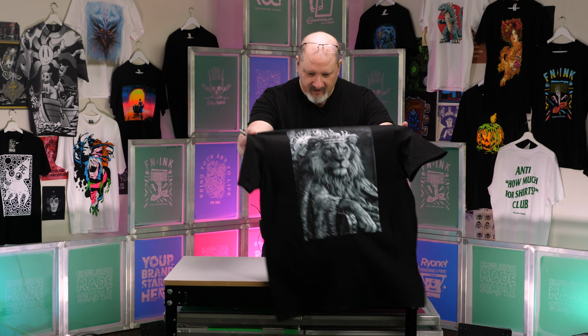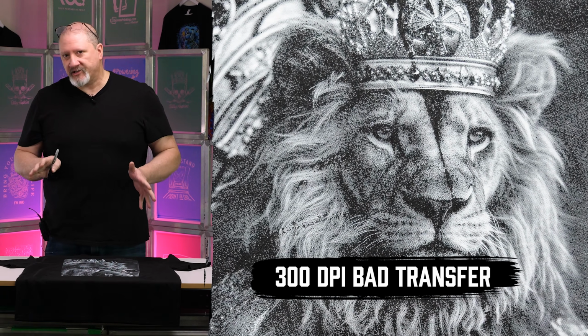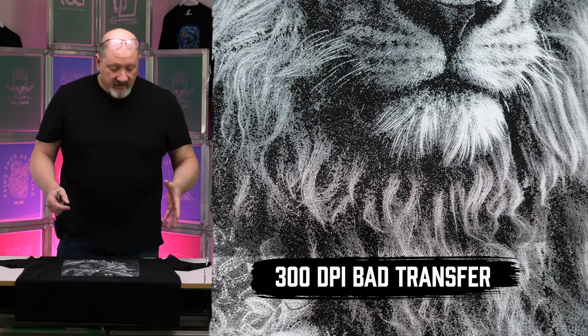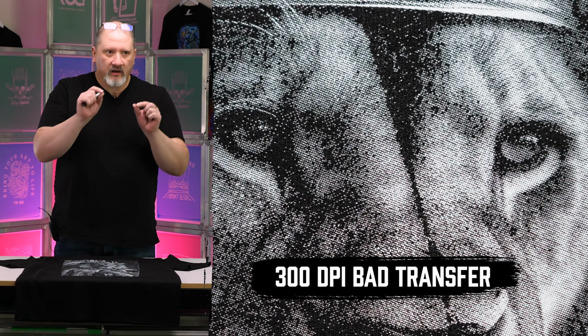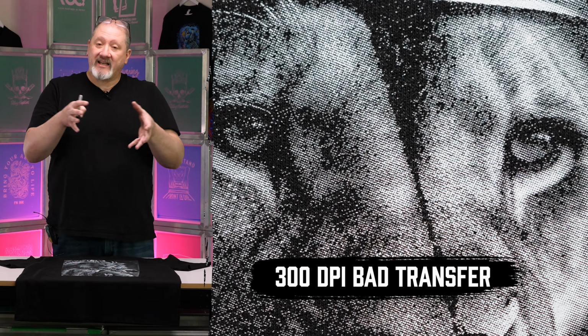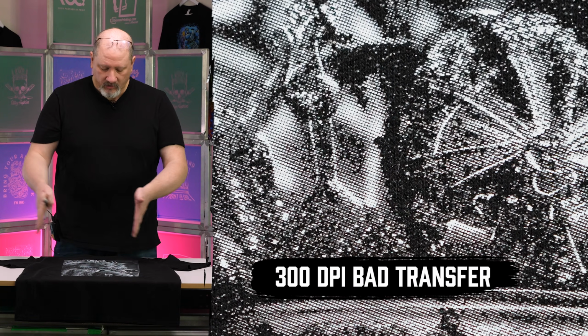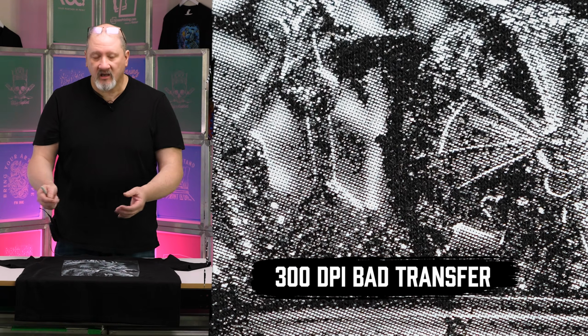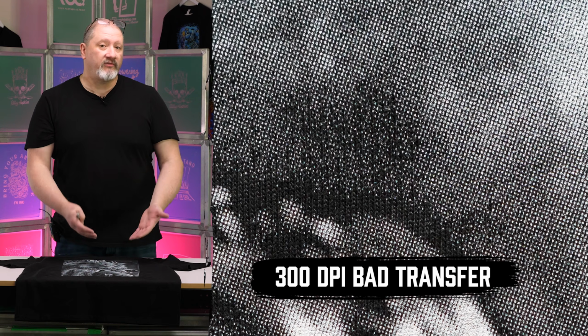This is one of the attempts for doing that 300 DPI halftone conversion. It didn't transfer as well as I wanted it to. I learned a few things in this with the amount of ink that's going down on the transfer sheet, and then the amount of adhesive that ends up adhering not only to the ink, but to the little bits in between, because we have so much ink going past into very tiny areas. We also have a little bit of humidity, moisture being created underneath that print head. So the better the film you've got, the more moisture it can absorb. It ended up grabbing a little bit, so I had a lot of glue there as well. So that was another learning curve that I had.